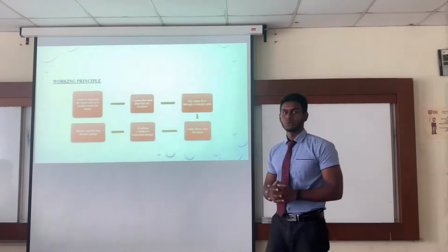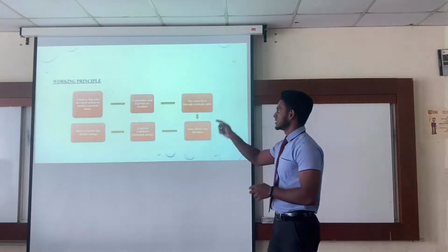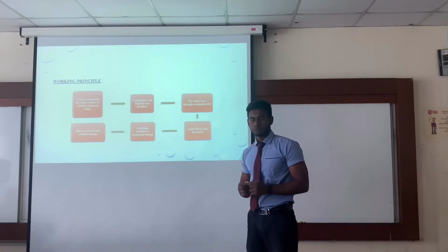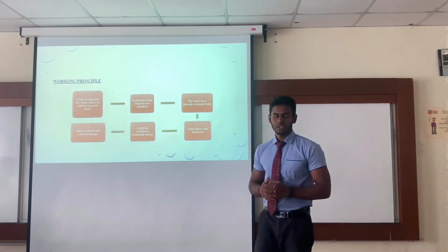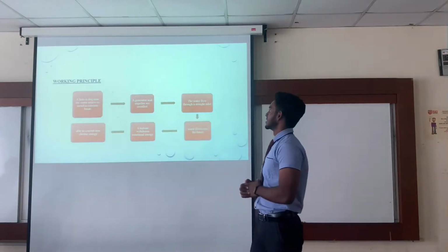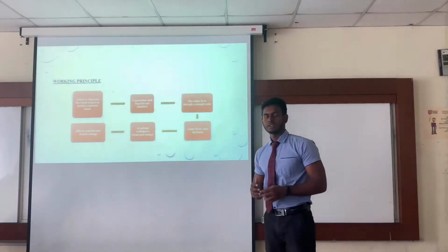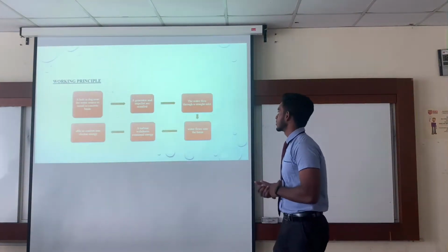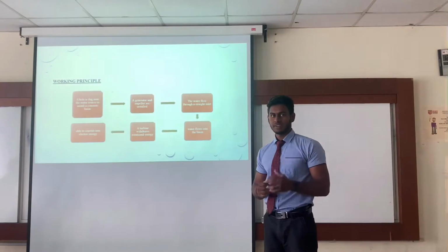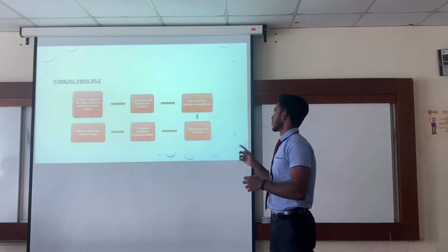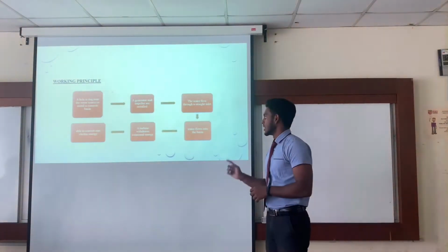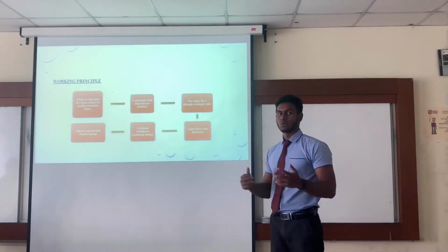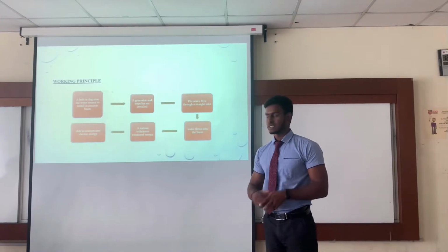The second one is the working principle. First, a hole is dug near the water source to install a concrete basin from a prefabricated part. Second, a generator and impeller are installed in the center of the basin. Third, the water flows through a straight inlet into the basin and the turbine withdraws the rotational energy. The last one is it is able to convert into electrical energy.